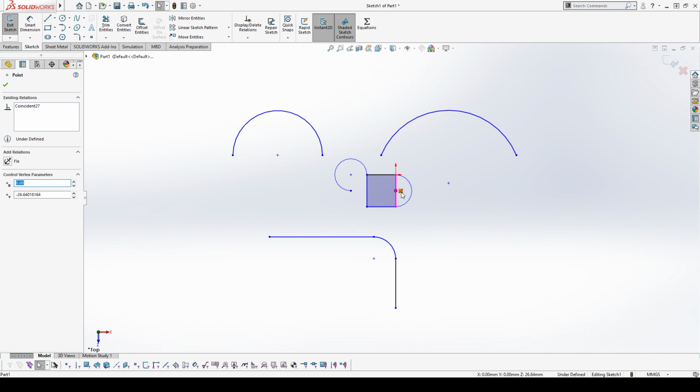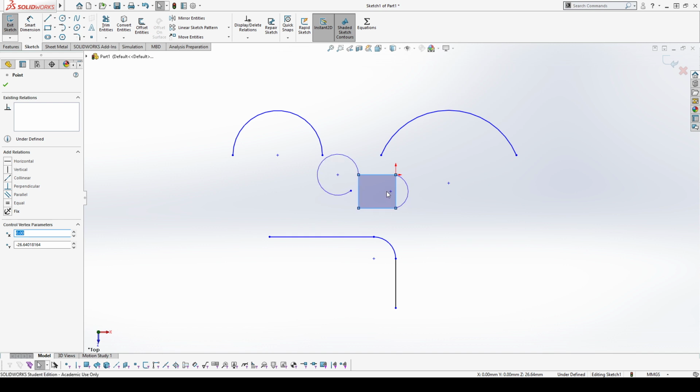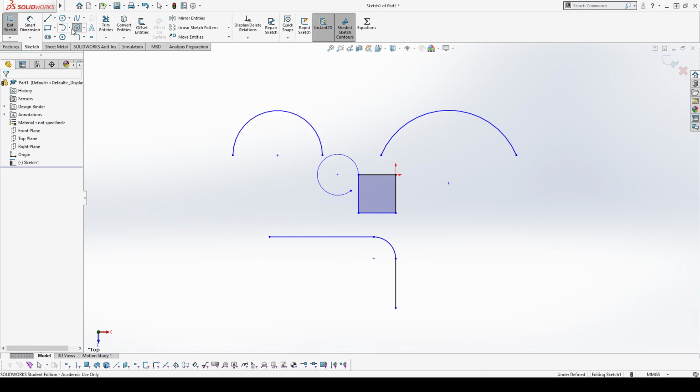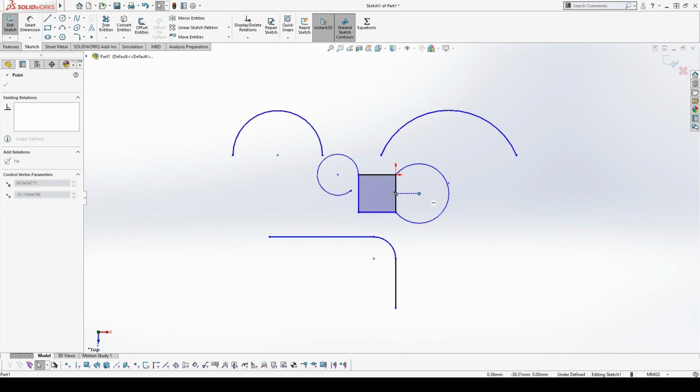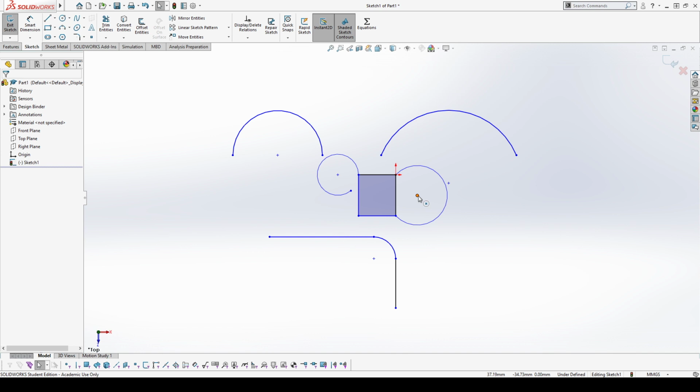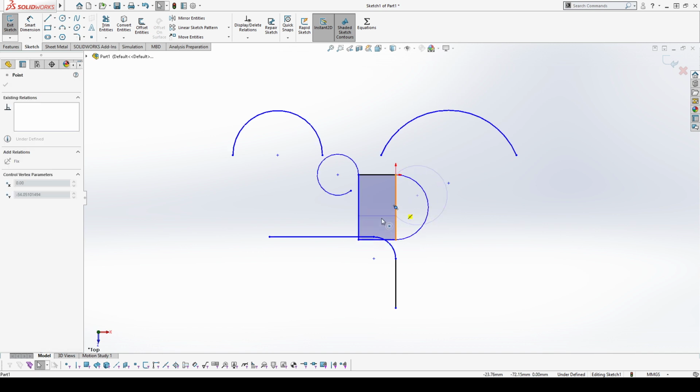So this point here, the center point of the arc, I made that coincident to that line. If I click on this relation and delete it, move. Yeah, there we go. I can actually move that point around. It's kind of finicky. Didn't want to let me do it, but yeah. Let's see. Added another 3-point arc there. 1, 2, 3. So that can be there. Also move it inwards as well. But yeah, SolidWorks is a little finicky, and that doesn't really want you to move that in.